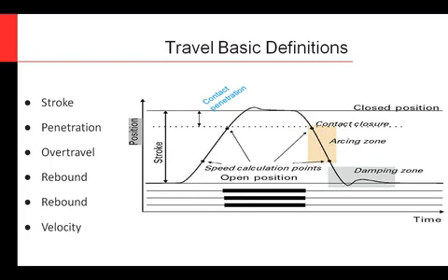But then once that coil releases the trip latch, as long as your velocity is okay, it'll have the energy to interrupt that arc. If you don't have enough velocity, you can have a problem where it's not timed correctly. You don't actually interrupt the arc, and the circuit breaker won't do its job. So it's not only important to check timing, but of course also velocity.